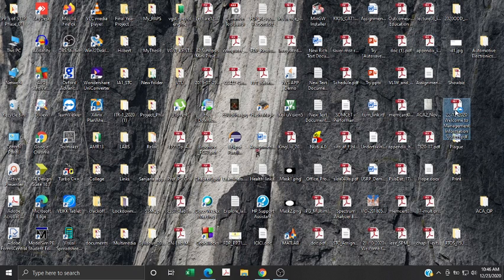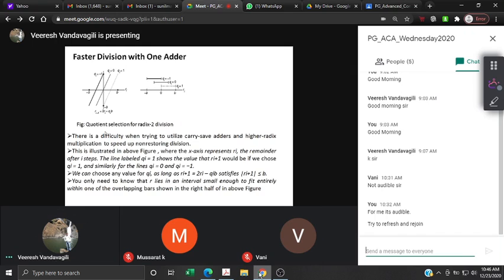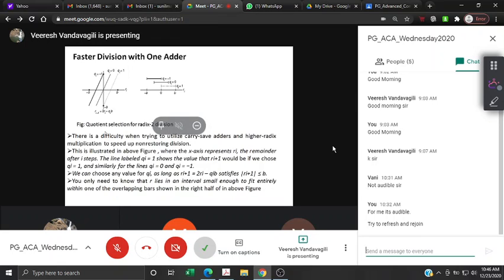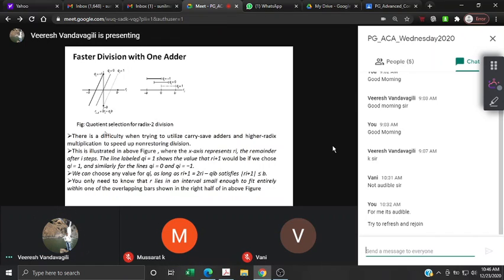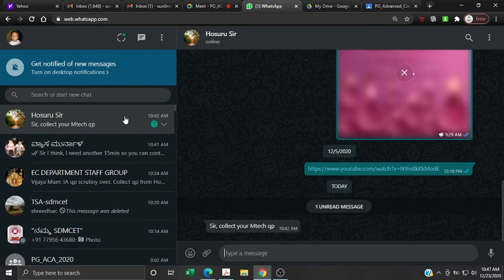In carry save division, the idea is that because the remainder is not known exactly, the exact quotient digit is also not known, but with the redundant representation of the SRT, the remainder does not need to be known precisely in order to pick a quotient digit.